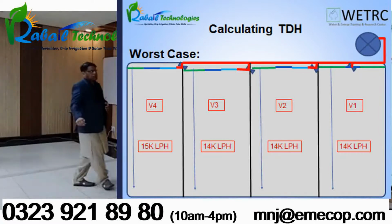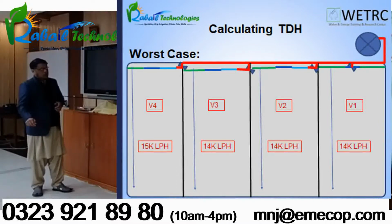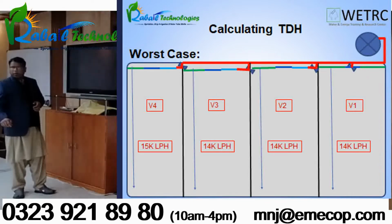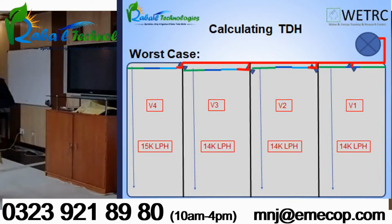Why? Because if we need to deliver 15,000 liters at this point, you see there is no outlet. These are the valves available, but all these will be in off position, they will be shut, because only one zone will need to operate. So if we need 15,000 liter over here, we have to induct 15,000 liter from the pump.